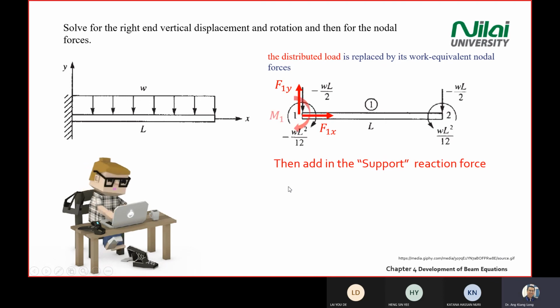Okay, right. So then we go back to this question. You add in the 2 arrows, which are the reaction forces for the wall, and we know that when you have something fixed to the wall, you have a moment reaction. So you add in the 3 additional supports there, right? The 2 arrows and then the moment M1.